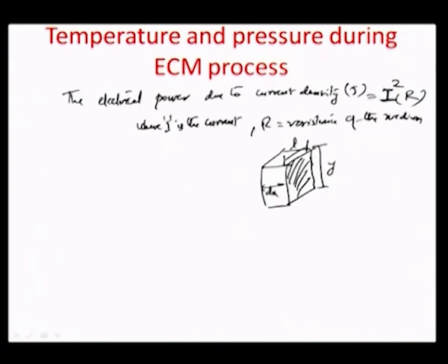So, therefore, the resistance here can be written down as 1 by k times length over area. Mind you, the current is coming perpendicular to this face, right. So, the length that it would face is y and the cross sectional area that it would face is dx times L. So, therefore, the total resistance would be equal to y divided by k L dx.